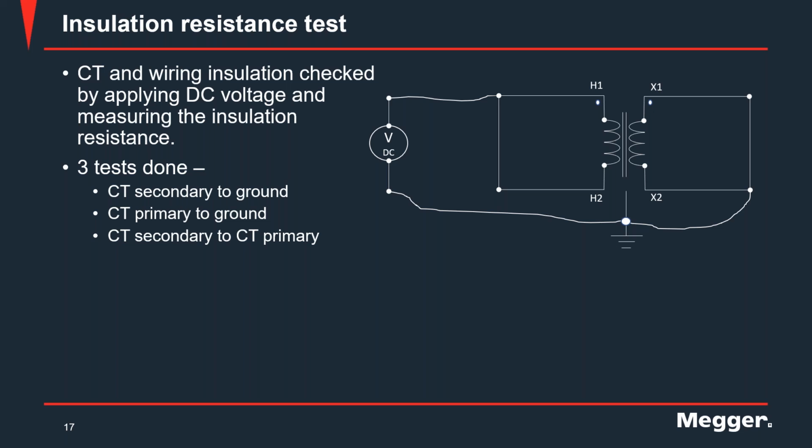All right, thank you. Volney, could you please explain a bit further the calculation of the knee point, because a 45-degree slope changes depending upon the scale. I was told that the knee point is the point where the slope is 1/5 that of the initial slope.